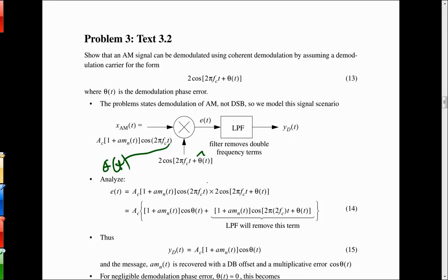Then there would have been a plus theta of t in here, and the reference would have had the hat in it, right? Multiplied. And then down in here, this would have been theta of t minus theta hat of t. If it was perfectly tracking and coherent, those two are equal, so that's approximately equal to 0. Does that make sense? Is everybody okay with that? Yeah, but since there isn't actually a theta t in the input. Right.